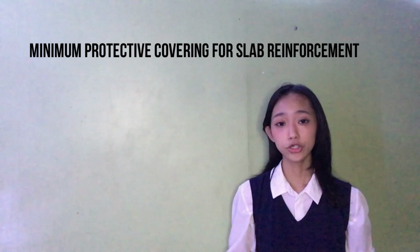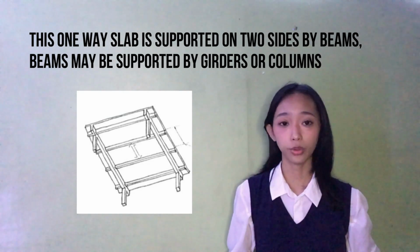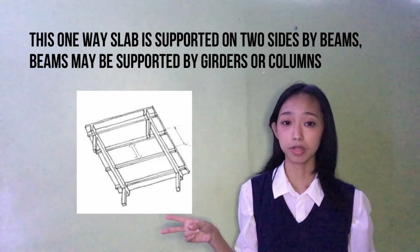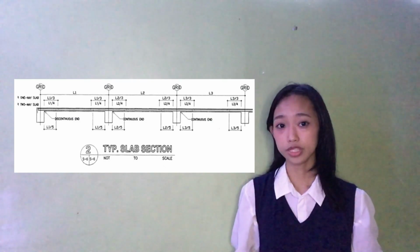The minimum protective covering for a slab measures about 20 millimeters or 3/4 inches. This one-way slab is supported on 2 sides by beams. Beams may be supported by girders or columns. Here we have a section of a slab.